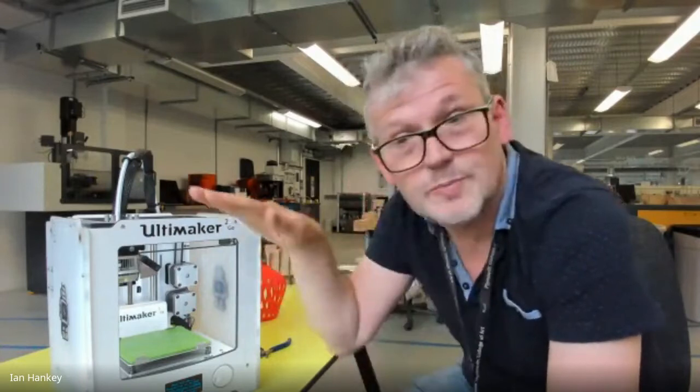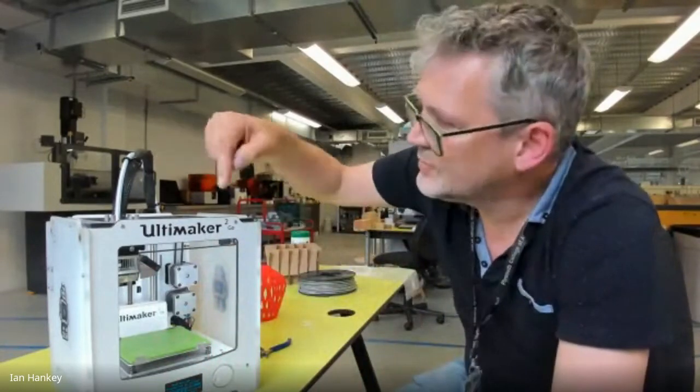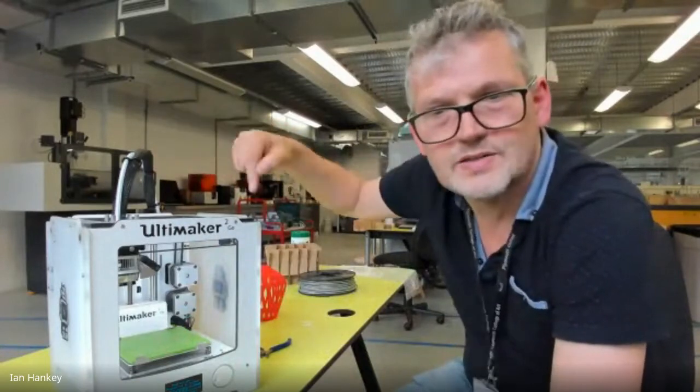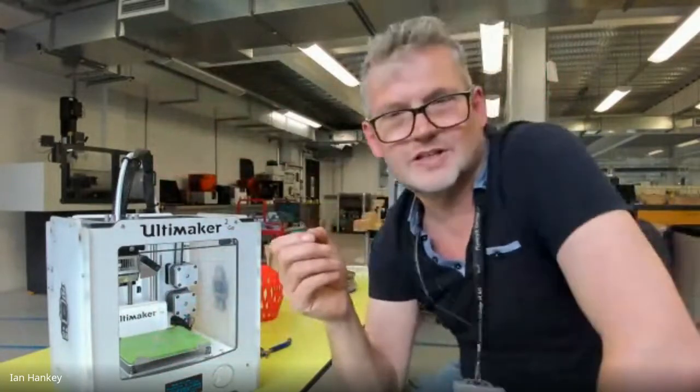So there are limit switches on this machine. Do you know when you put your printer on at home and you turn it on and it whirs around like a mad thing for ages? Well, basically, what it's doing is it needs to find out where to start before it can start printing. So the bed went down, didn't it? It's gone down till it's hit a limit switch, so it knows that's where it should be to start. The print head uses an X and a Y axis, and it's gone into the bottom left corner if you think of it as a page. Most origins are usually in the bottom left. So it's now sitting, if we're looking down on it, in the bottom left corner. It's hit a couple of limit switches there as well, so it knows where to start, basically.